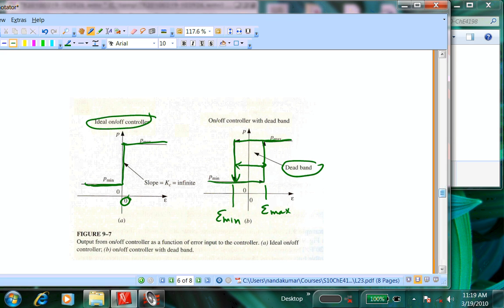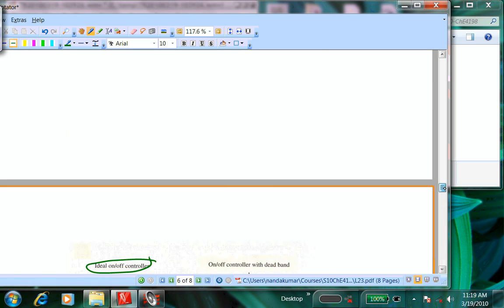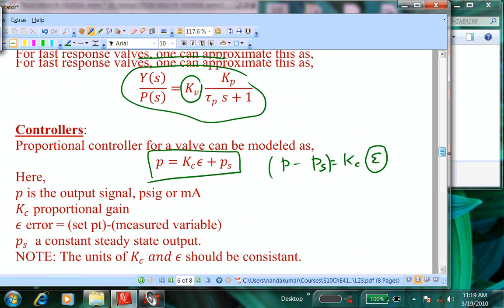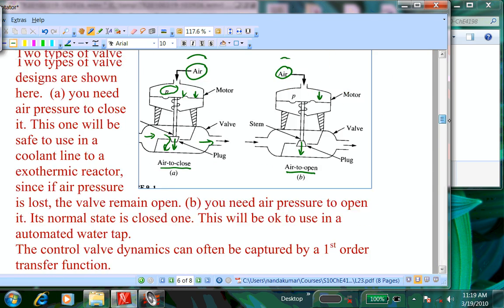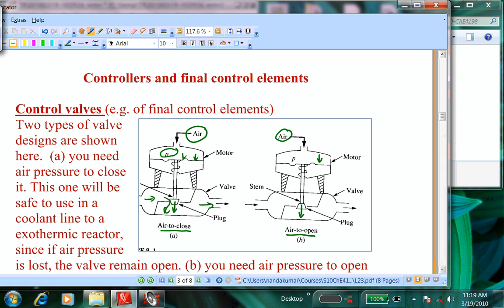for example, if you go back to this valve, so now we are the valve manufacturer. Okay. So if you need the flow to be continuously changing as you change the height of this, a process requires that, then you would design this valve to have this taper, right? So that depending on the extent of penetration, you can control the flow rate. But if you want on-off, how would I change that?